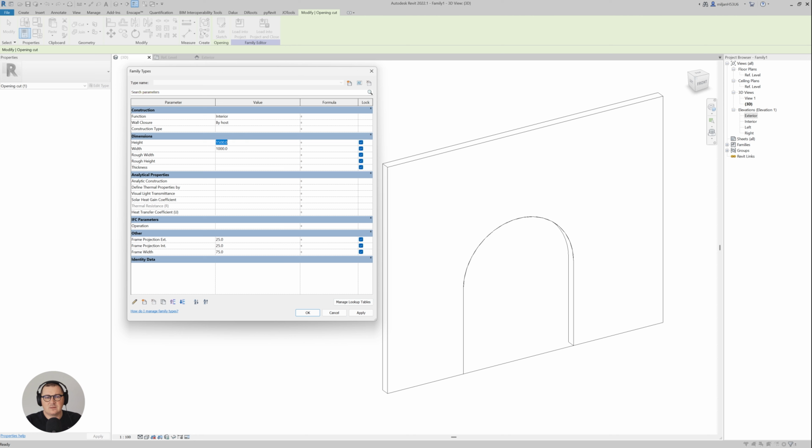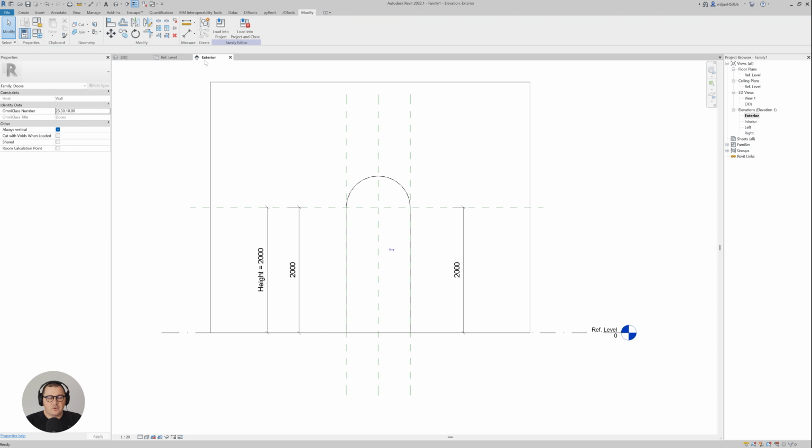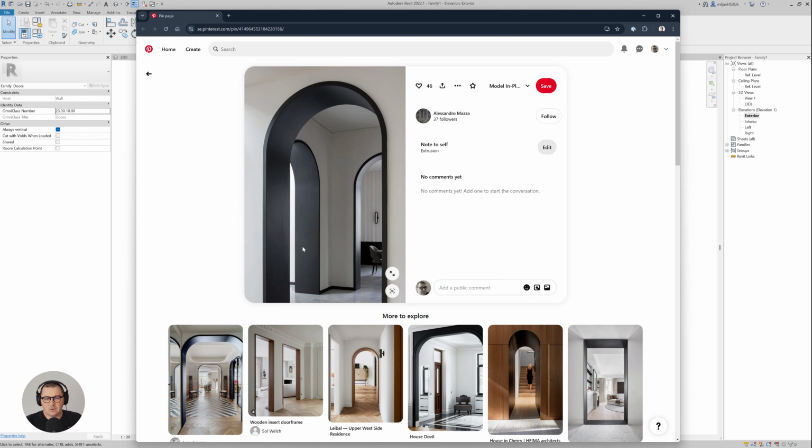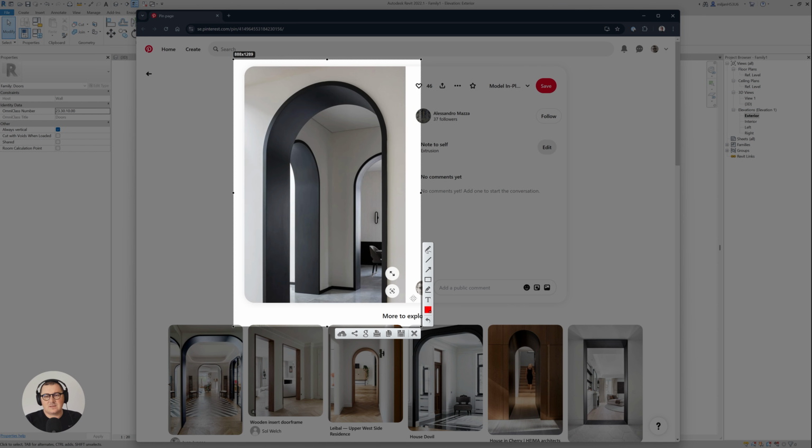So I will just bring everything back, and then I will go to exterior view, and I'm going to create our profilations. So as you can see here, in this case, I'm gonna take sweep tool. The reason is because we have this profile, and then that profile goes along this opening. And what you will also see here is how I'm going to adjust the parameters for this opening. So you can see that I can control its width. I can also control how much this sticks out.